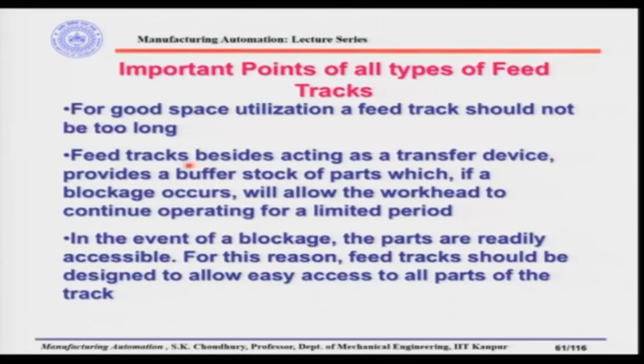The next point is that feed tracks, besides acting as a transfer device, provide a buffer stock of parts which, if a blockage occurs, will allow the work head to continue operating for a limited period.